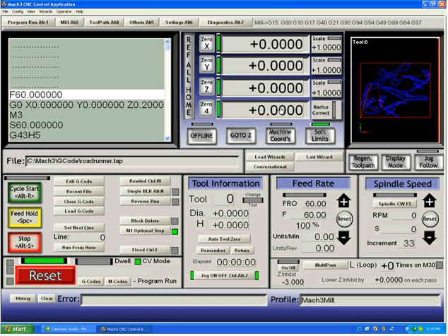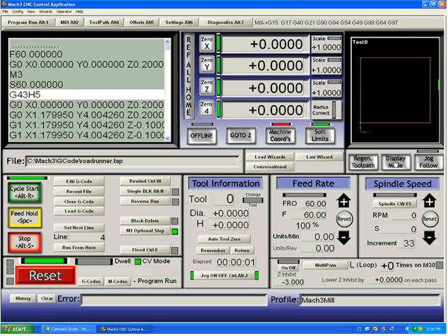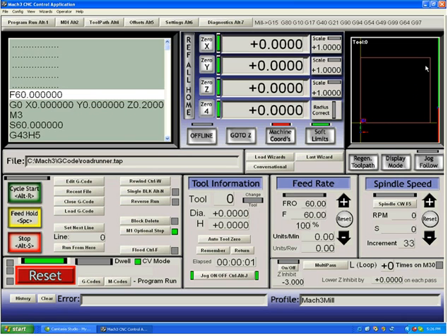So, first thing to be considered when we talk about machine coordinates is what do they mean in relation to your table? Well, we have a button here called Display Mode, which will switch me to look at my table. You'll notice when I pushed it, I now have a large red box, which is no longer displaying the outline of my program extremes. It's showing my table extremes. My table is programmed in the program right now to be 100 millimeters wide and 100 millimeters in the Y. So this is showing me a distance of 100 millimeters across the X and 100 millimeters across the Y.